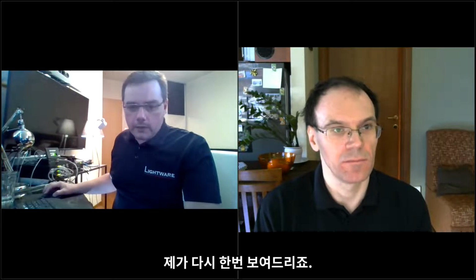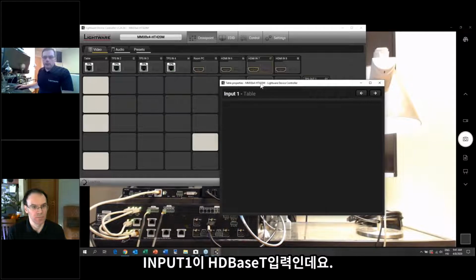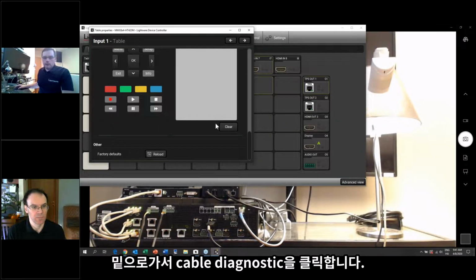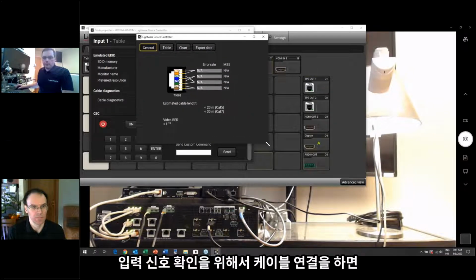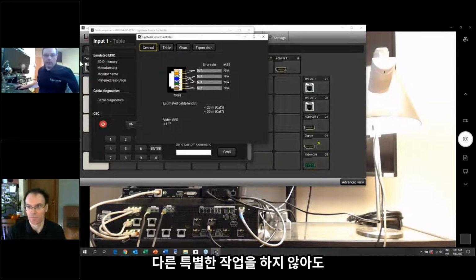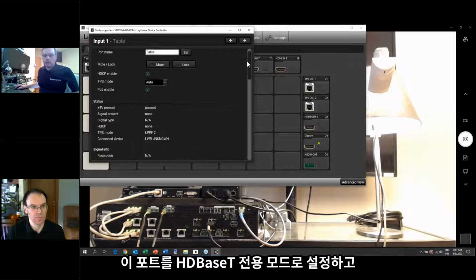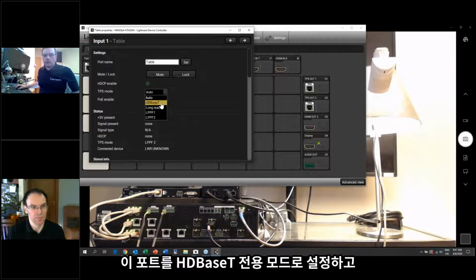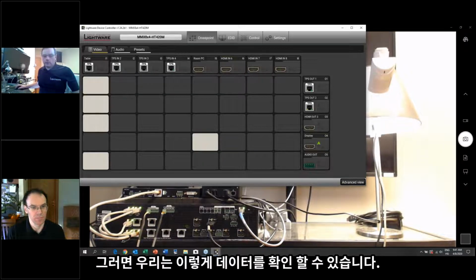Actually, let me jump back again. So I share my screen and get back to crosspoints and table. This is my HDBaseT source. Let's scroll down to cable diagnostics. That's what we need. I put a signal just to have an incoming signal. But okay, do it in a different way. You don't have anything here. Why? Because we are in automatic mode. If I set this port to HDBaseT mode all the time, then it will be connected all the time. So let's close this box and have this.